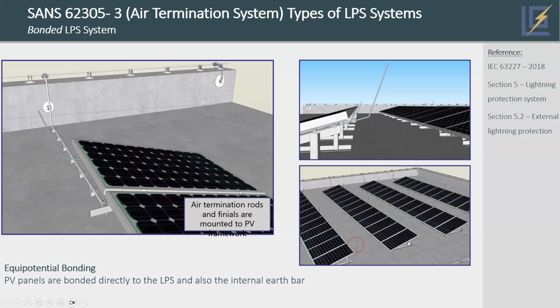And then you've got a cable running into your P9000 cable tray, which goes down to an earth rod, and then, of course, it gets equipotentially bonded. But what we find is, because of the waterproofing on the roof, and because of the anodizing on the clamps these days, because they're not really galvanized, there's no continuity.